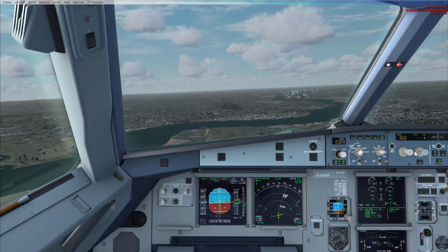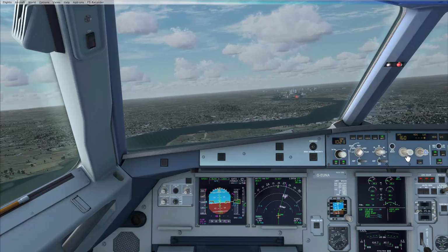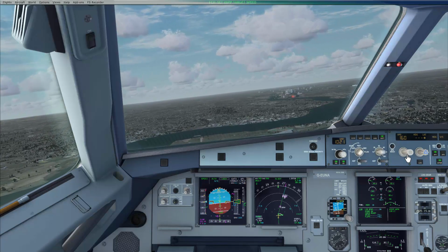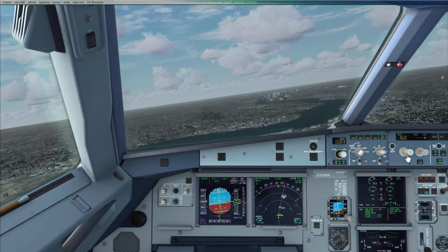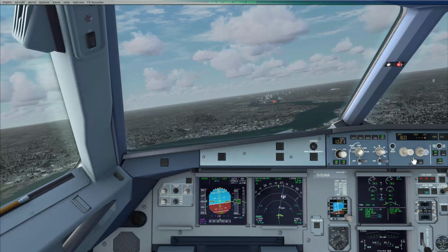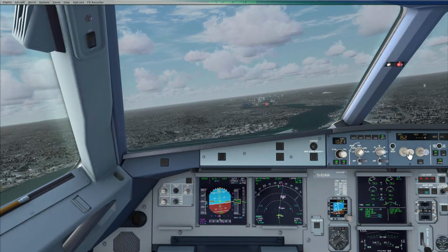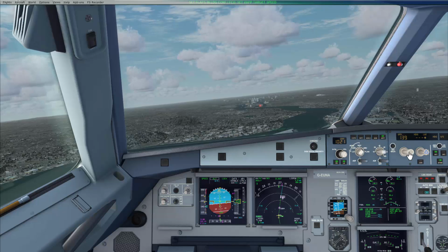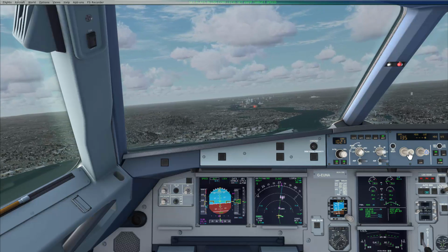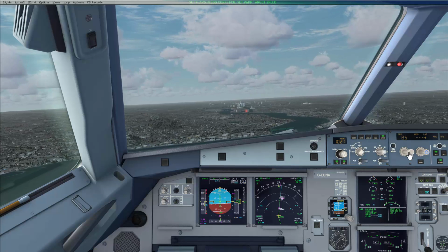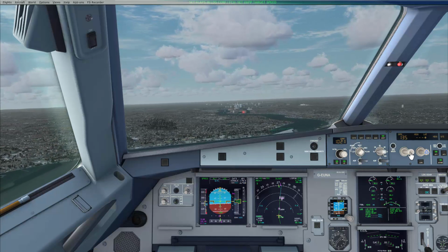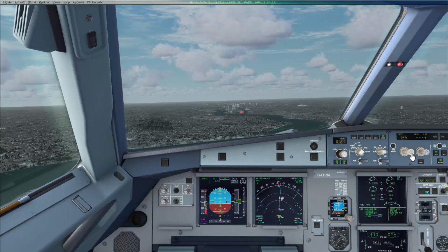Gear down. Gear down. Having reached our waypoint now, we have an instruction or a reminder at the top of the screen to set the VAP target speed. So dial in 135. Flaps 3 now. Speed check, flaps 3. Flaps full. Localizer capture check, flaps full. Speed brakes full. It's all set.